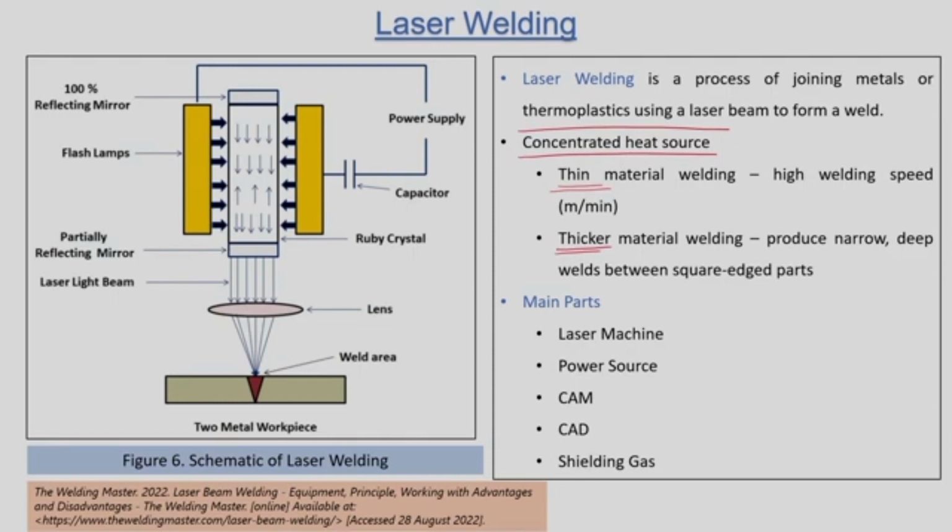If the speed is low, then there is a chance of cutting the thin sheets, and we will not get the welding done. There may be vaporization and the thin sheets may get cut, separated, or parted off. So, we have to increase the speed of the laser material interaction, so that enough heat is transmitted only for the melting operation, not the vaporization operation.